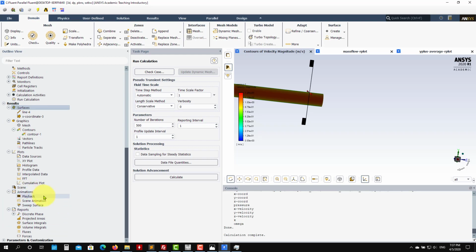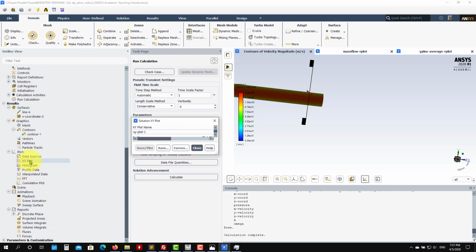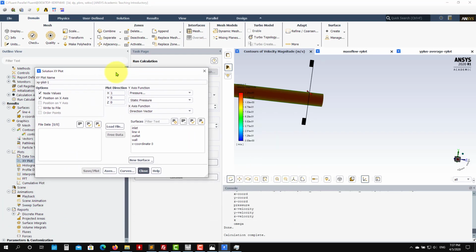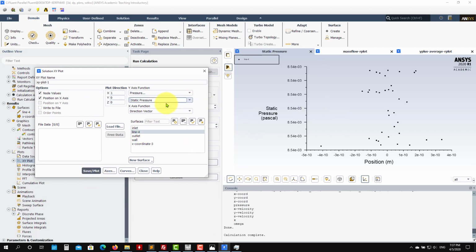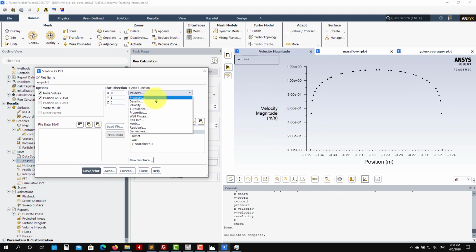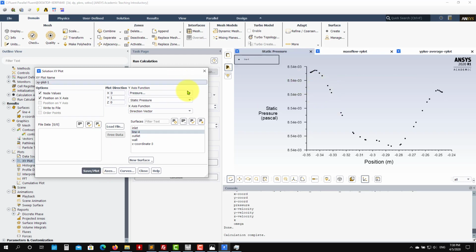Reports, plots. So as we go here, XY plot, like within this 1D case, you select that line, and for instance, plotting, oops, I don't recall the, okay, velocity. So here again, you need to choose the right axis. Okay, this was the one. So see the velocity profile. So you can compare with the 2D case. We should get something similar, okay? That is part of your homework, let's say. It's not a formal homework, just check that one, practice.